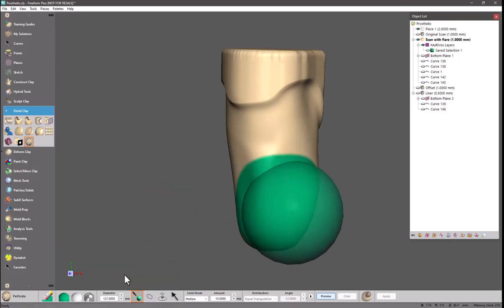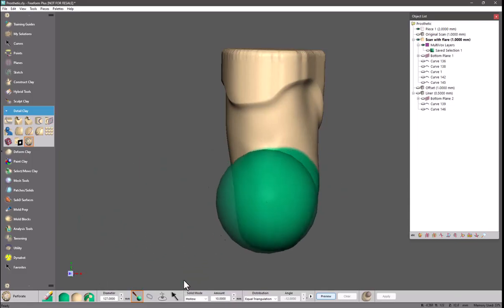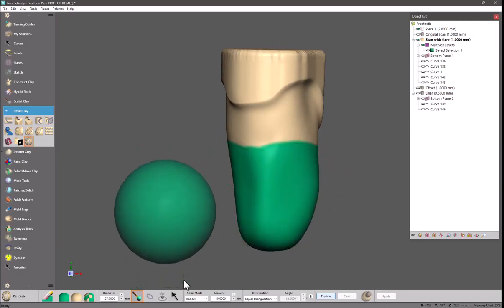The tool provides several different ways of selecting where you want to perforate your model, so you can paint your selection. There's curve selections, these are curve loops. There's a seed point selection tool which coincides and works with the curve loop selection, or you can select existing points which are annotation points already created in Freeform. Right now, this is not exactly what we're looking for, and trying to paint a complex selection is a little challenging, so oftentimes you will use a combination of tools to do this.